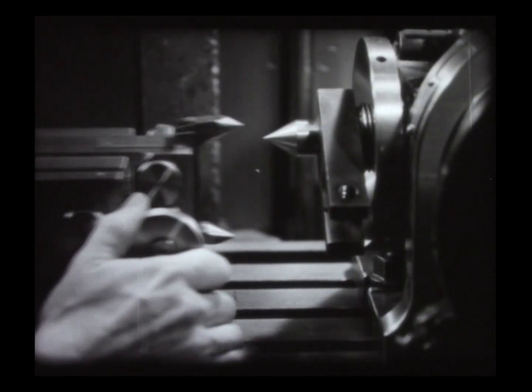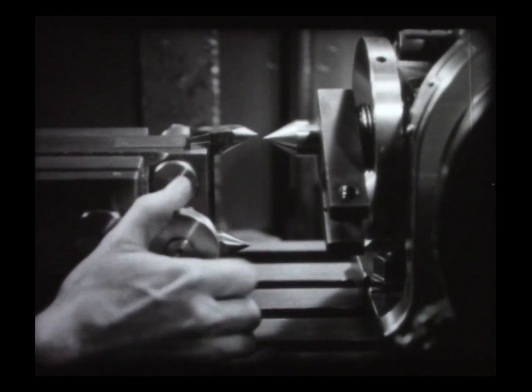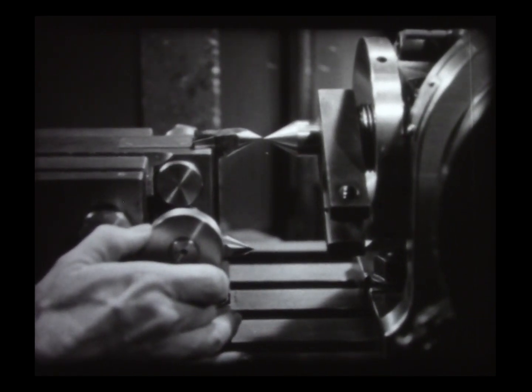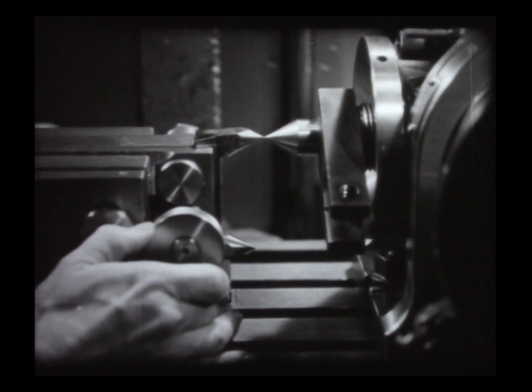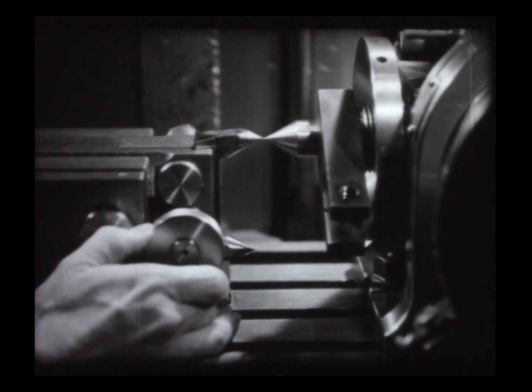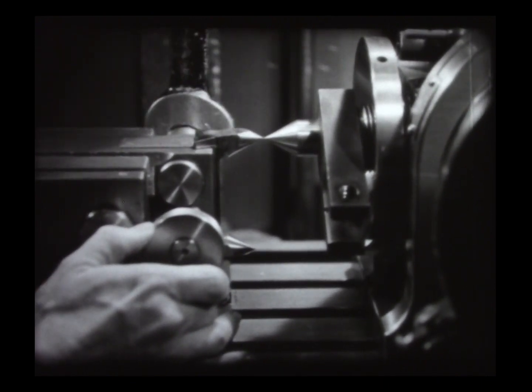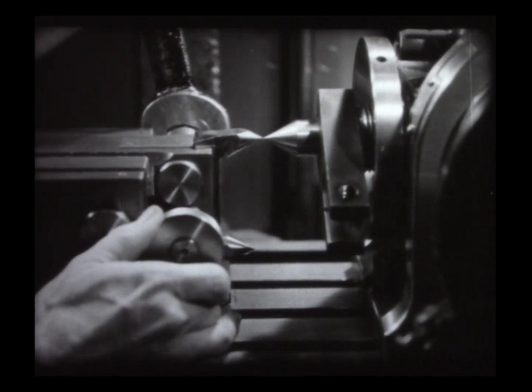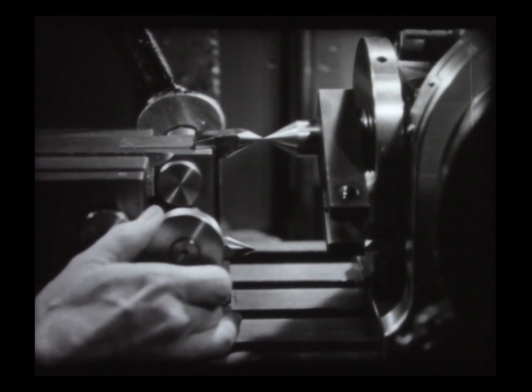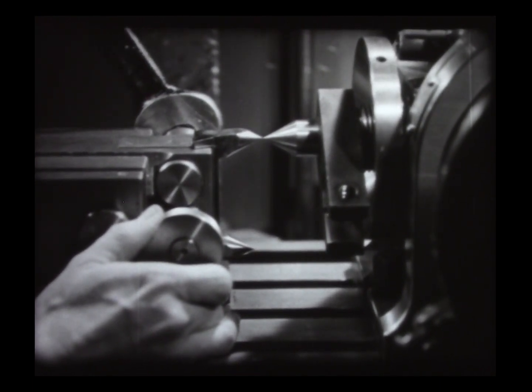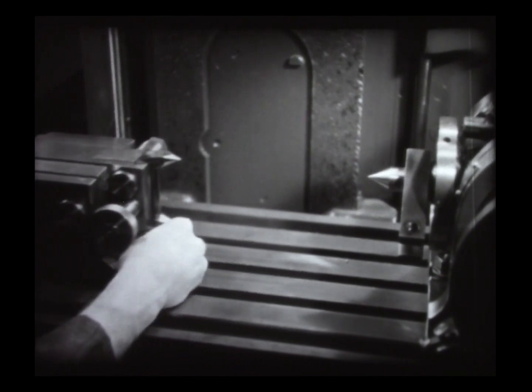Before placing the mandrel between the centers of the dividing head, the tailstock center is lined up squarely with the headstock center. Sufficient room is left between them to hold the mandrel before the tailstock is secured to the table.